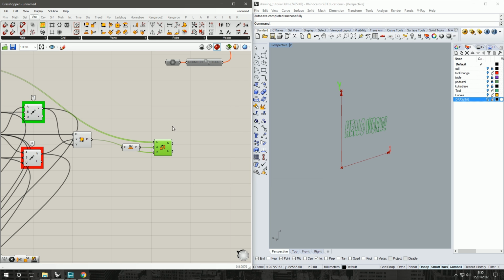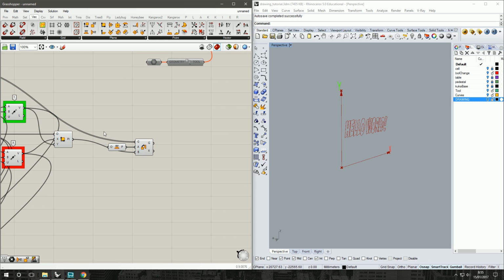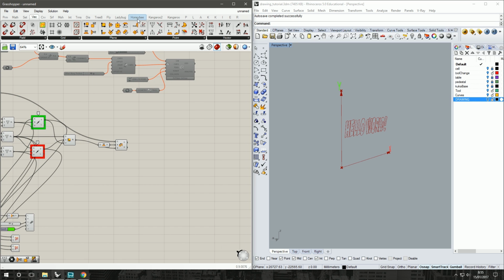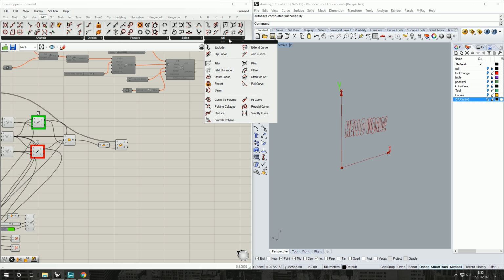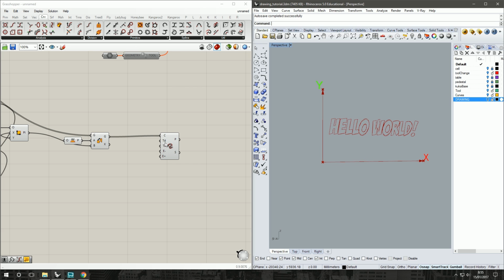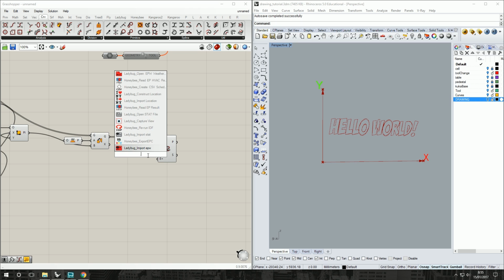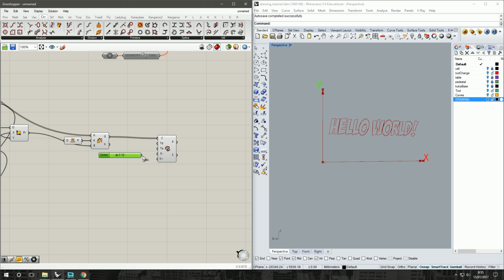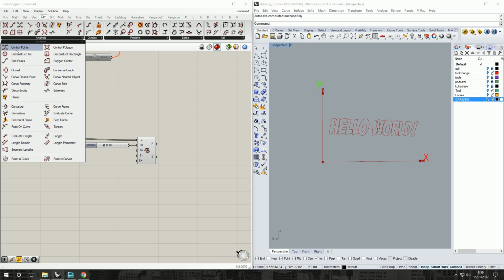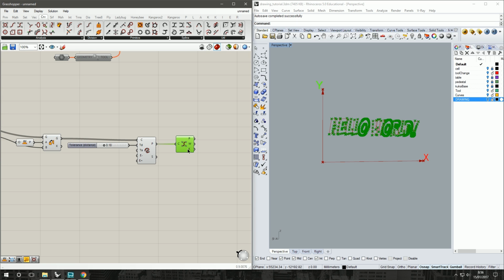So now that we've got our information, our curves properly orientated, we need to set up the paths just like we did in the previous step. So we'll go through this nice and quickly. We've got our KUKA. We need to convert our curves to polyline, which is under curve and utilities. Our curves are the ones that we've referenced on our new canvas area. For the distance from the last one, we know we want to use 0.18 or whatever suits depending on the curves that you've drawn. Beautiful. So now we've got our curves. Now we need to put on the control points, which is curve analysis control points. Got our points to reference.